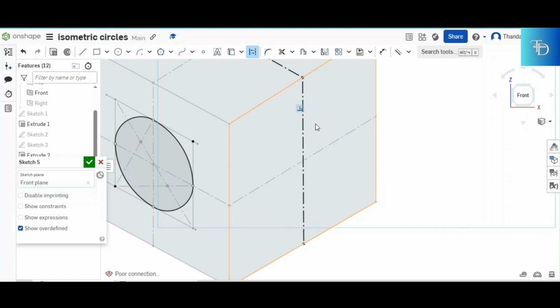Since our diameter is 50, we're going to have to create a square that is at 50. You know the drill. You have to mark from the center because we have a center point there. You have to mark from the center 25 millimeters. You mark another 25 millimeters at this side, all equals to 50. And then from the center, you deal with the vertical now. You mark 25, you mark another 25 right there.